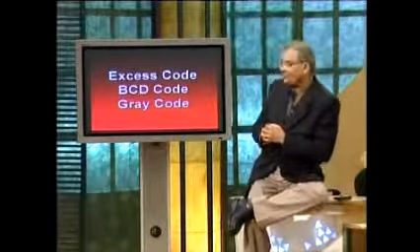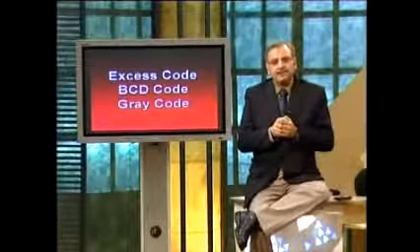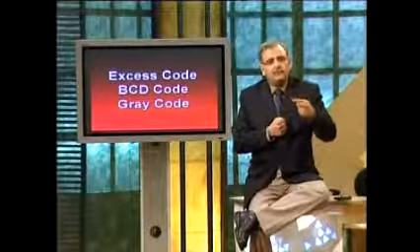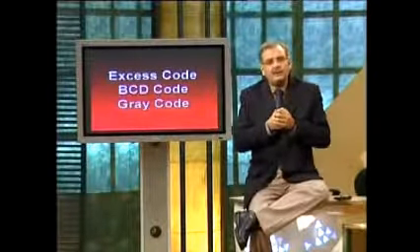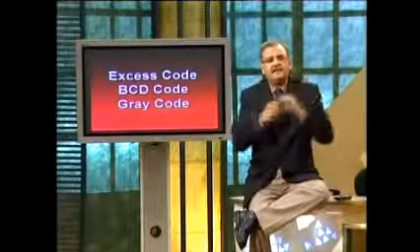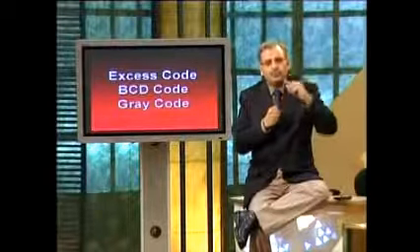The third representation, the gray code representation, let's have a look where do we use this gray code. Now, if you look at the binary code, when you, let's suppose, count from 2 to 3, how many bits change? Only the first or the least significant bit changes. Let's suppose you are counting from 7 to 8. How many bits change? Well, 7 is 0, 1, 1, 1 and 8 is 1, 0, 0, 0. 4 bits have changed. Now, in certain electromechanical applications of digital systems, you would like to keep the bit change to 1 when you count up or down to the next successive value.